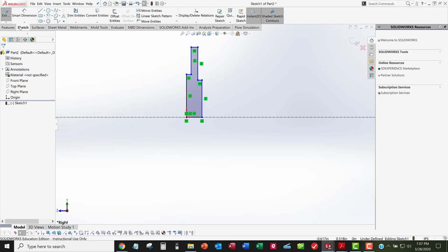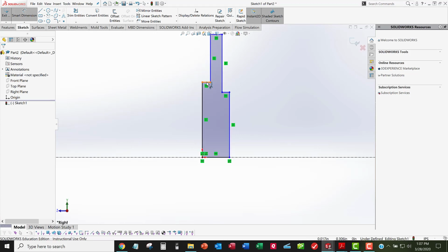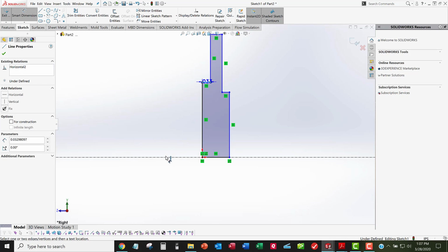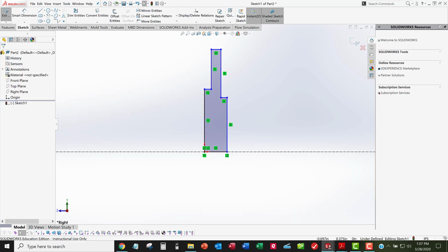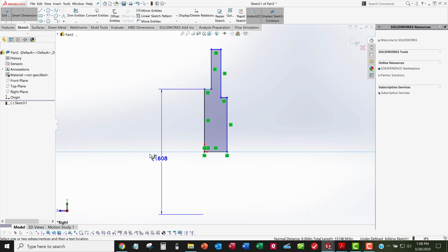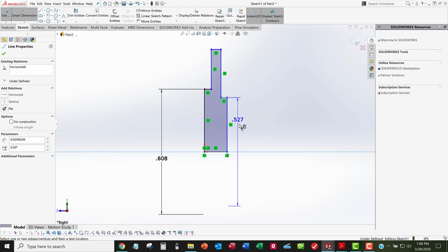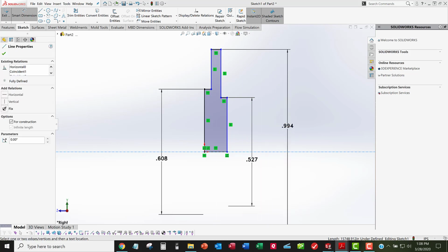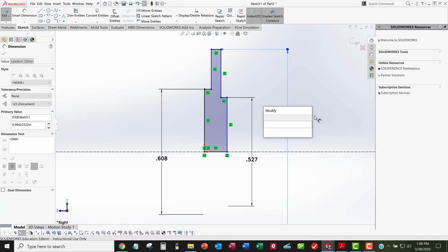And so we'll use my smart dimension, and if I'm smart and I dimension to the center line, what happened here? If I dimension to my center line, I can do one of two things. I can do a radius. If I don't click here and I pull down here, it'll display as a diameter, and that's what I want. I'll do the same thing over here. Since I've already selected the center line, it assumes I still want diameters, and so I'll put all these diameter dimensions on here, and now I'll go back and look at my WR34 waveguide.